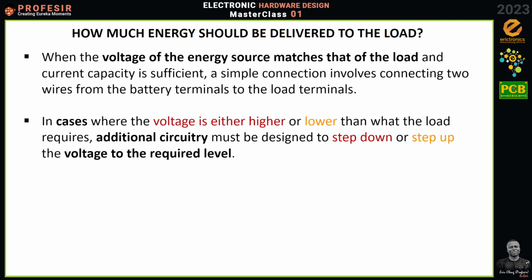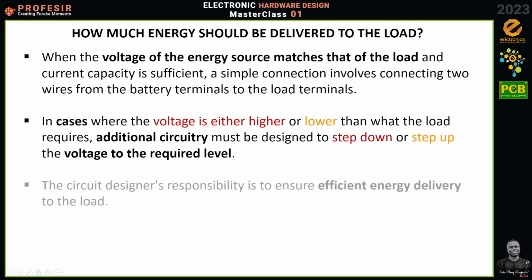So in cases where your voltage is either higher or lower than what the load requires, then we will need additional circuitry to step down. So we will step down if the voltage is higher, or we step up if the voltage is lower, okay, until we meet the requirement.